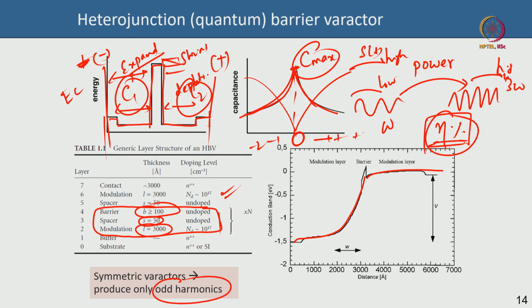Okay. So, with that I think we can conclude lecture 10 on varactor diodes and Schottky multipliers. We understand that these are devices where capacitance can be tuned non-linearly by applying a voltage, and by doing that you get a tuning element which you can use in a resonance circuit and tune the frequency in an oscillator.